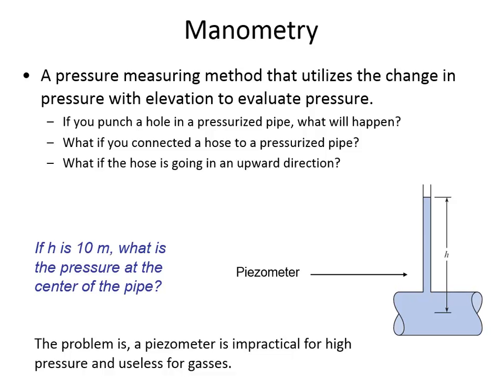All right. Well, let me just mention this final point before you go. The problem with the piezometer is it's open to the air. Think about if this was the way they were trying to measure the pressure in the pipe in Huntington. Typical water pressure would mean that this tube is rising 51 meters above the pipe. And so people would have to walk around on really tall stilts to read the pressure, or maybe use a surveying level. The height is too tall, and so that's one thing about it, its impracticality.